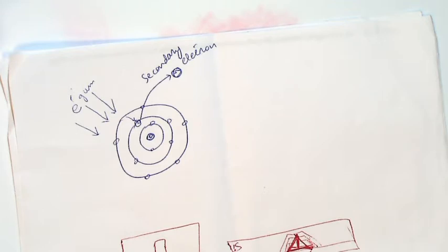You shower electrons with an electron gun on a small area, and exactly the same way, those electrons will hit the electrons from the material, and some secondary electrons will be generated. You have a detector there which detects only the secondary electrons being ejected from the material. So in a certain area you will have more ejection. For example, if it's a high feature close to your gun, or a lower feature, you have different electron ejection as secondary electrons. So with the gun you are accumulating small areas where more electrons or fewer electrons are being ejected.